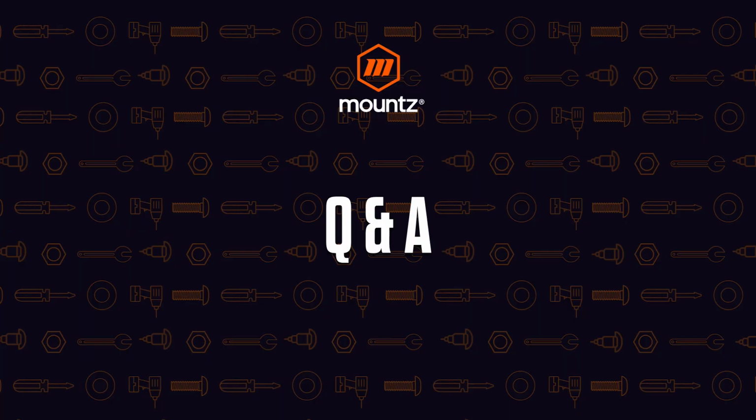All right, Dave. Another question we had was, can you speak to why angle measurement isn't a calibrated function? So again, when we're looking at fastening and the use of angle, what we're doing with the angle can be correlated to the prevailing torque. We're basically removing friction influencing the amount of torque that is being generated.